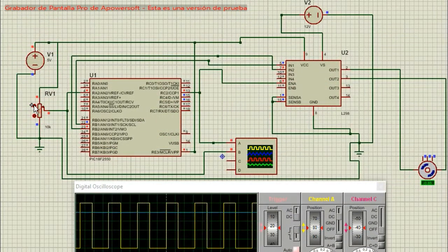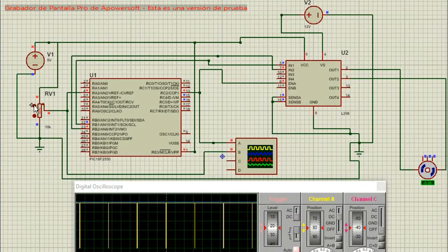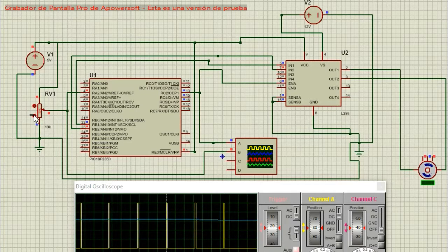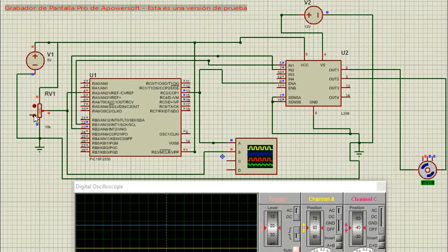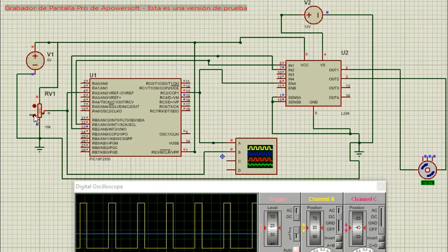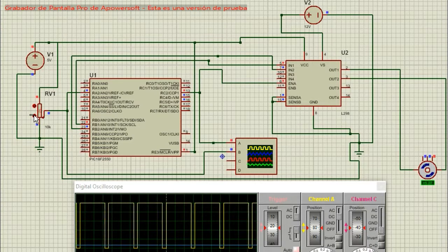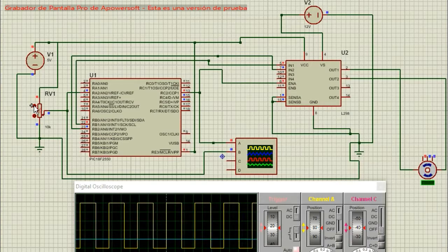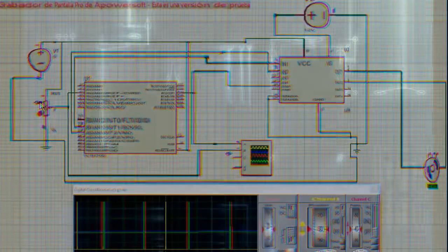This consists of the ADC values of the potentiometer being kept in a range of 410 to 613, where the motor is stopped. It turns to the left in the range of 409 to 0. The motor also spins in the other direction in a range of 614 to 1023. This was done in this way.